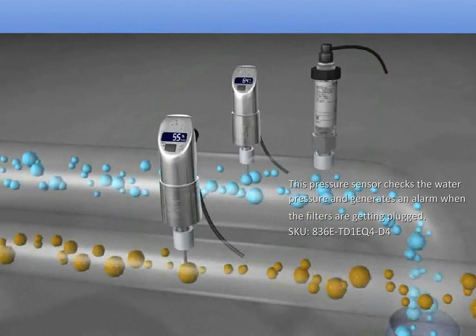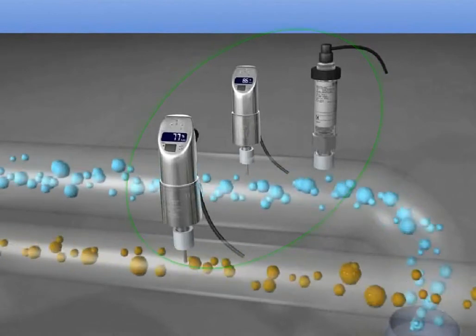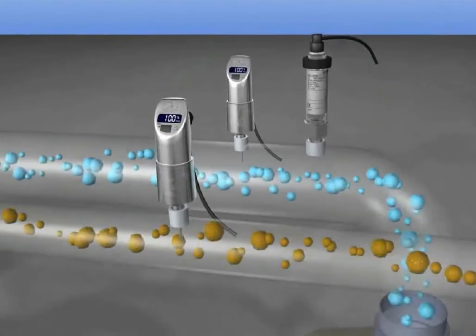We are also using an 836E non-display pressure transmitter to check the water pressure at the permeate water pipe. A decrease in pressure indicates when the filters are getting plugged, and that it's time to backflush the filtration membranes.